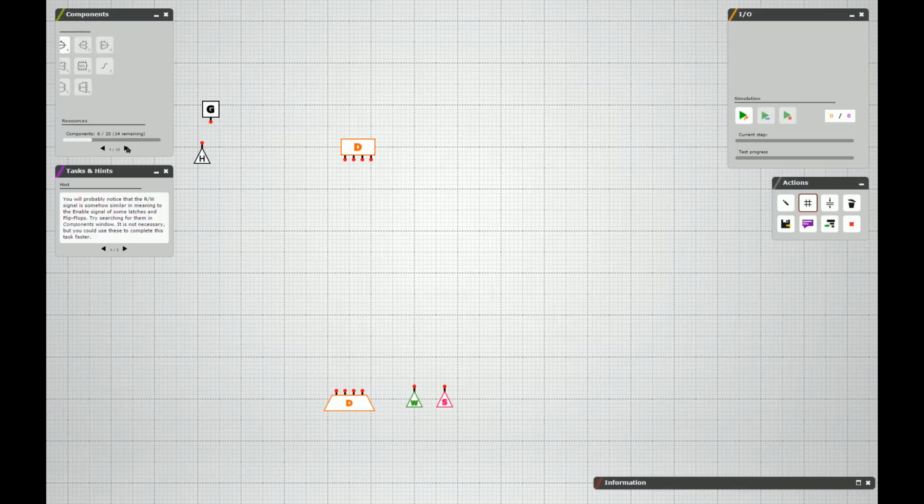These are our multiplexers. Basic arithmetic. Here's our latches. So here's the SR latch, which doesn't quite do what we want it to do. But they've given us a new thing called the D latch, which is the first latch to at least distinctly resemble the nature of memories. The D latch stores its internal state, accessible through outputs Q and Q bar. Input E, or enable, enables storage of the D data input, so that D is stored only when E is 1. That sounds like exactly what we need.